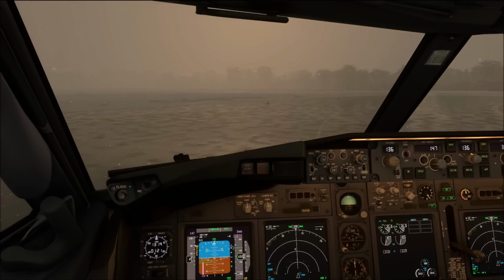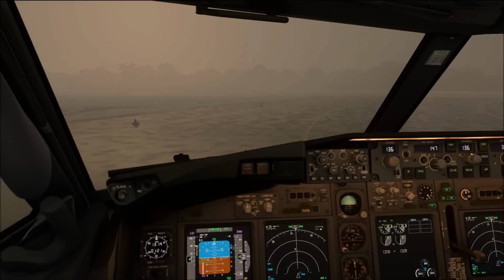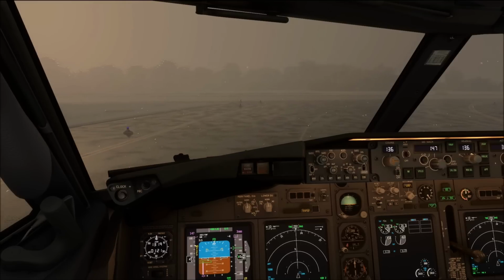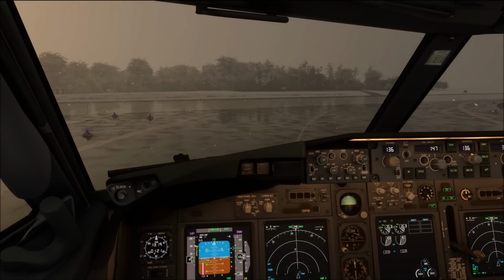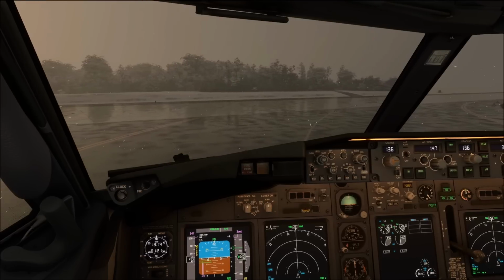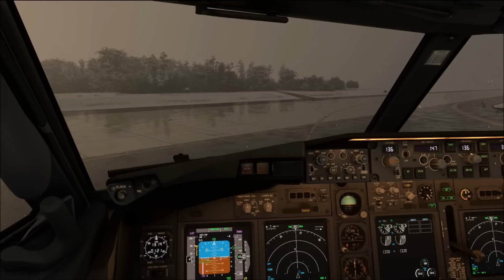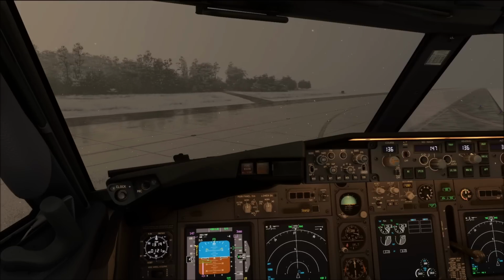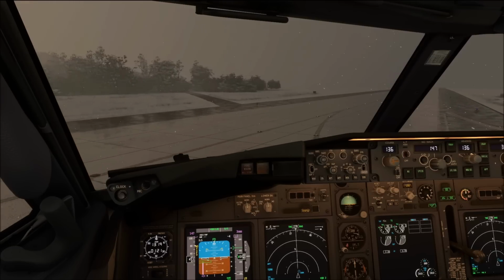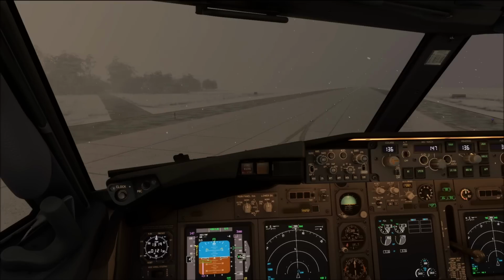There have been a couple of accidents, and let me just name one of those. A European operator that flew a Boeing 737-800 into a Polish airport at some point in the winter of 2021 to 2022 had to roll out all the way to the end. The crew, aware of the bad contaminated condition of the runway, initially slowed the airplane down to approximately 40 knots, about halfway down the runway. In this time they figured out the runway had good braking action and they could brake the airplane without any problems. However, they had to roll all the way to the end.